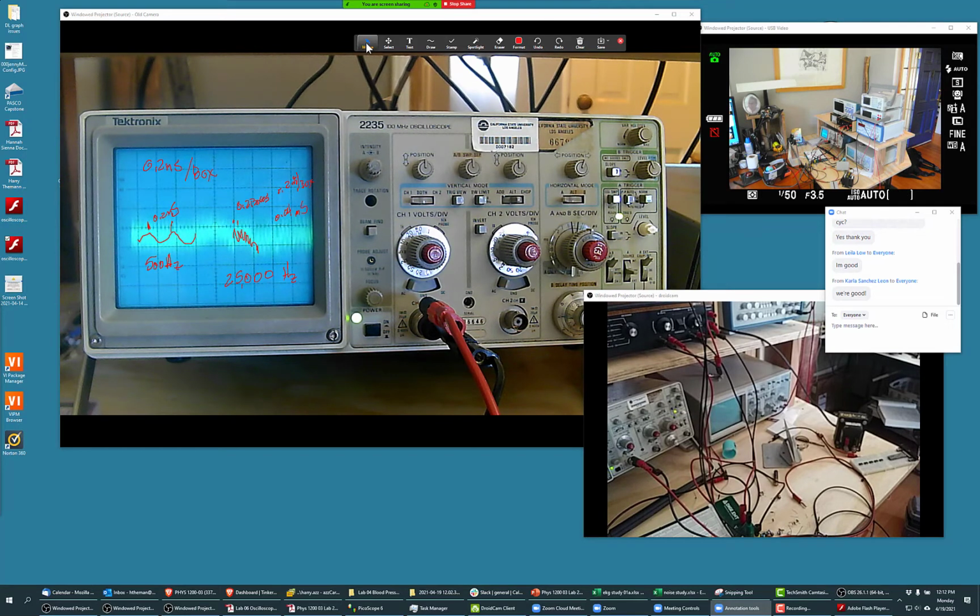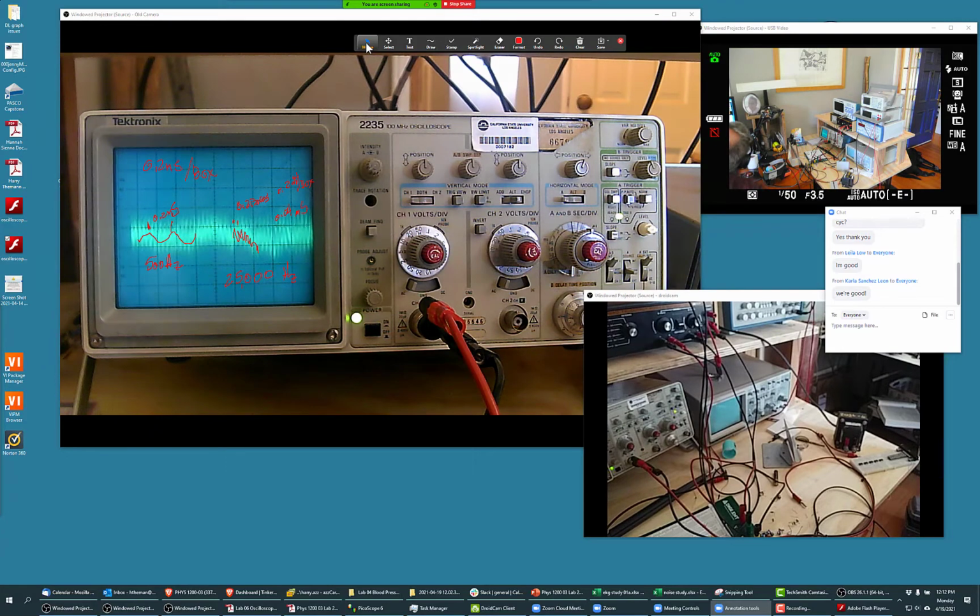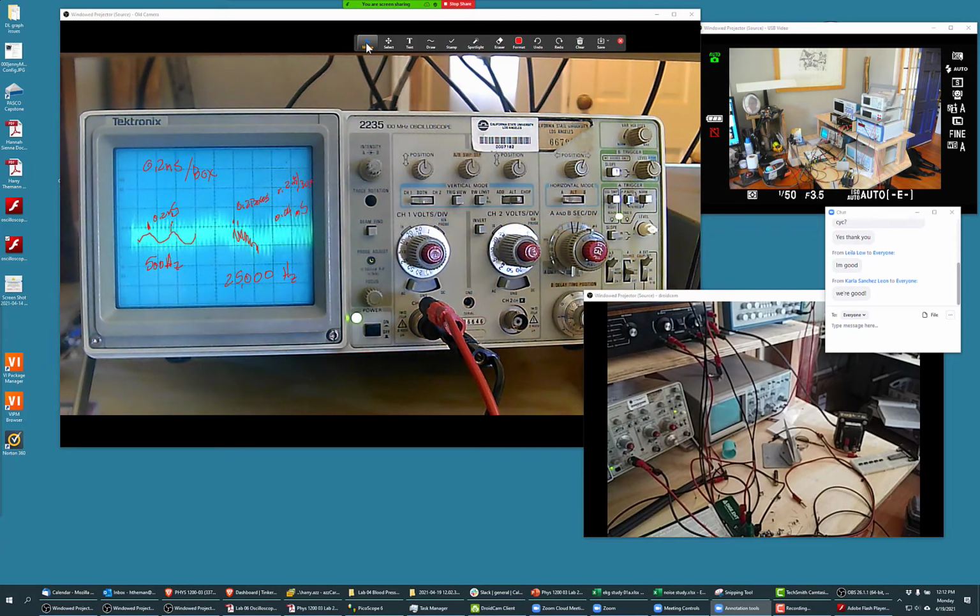I turned around and I noticed I'd left the oscilloscope on. And I turned the light back on and I said, well, wait a minute, look at that. And then I flipped the lights on and off. I'd been trying to find this noise for months, and it was just the fluorescent lights. I was so annoyed at myself.